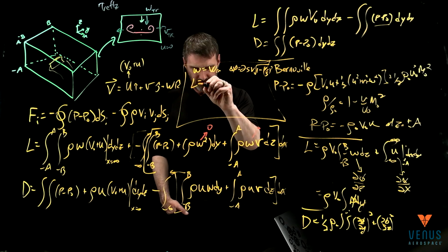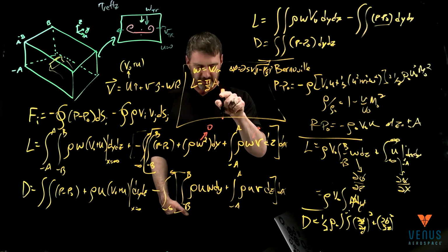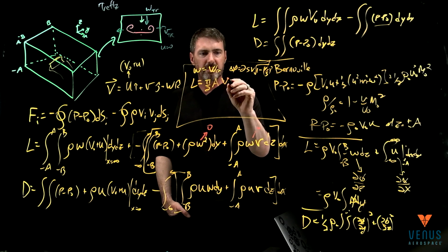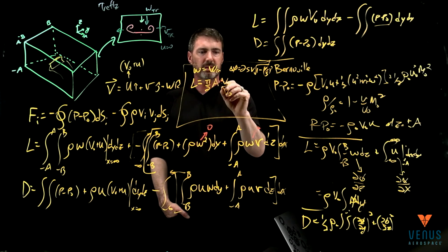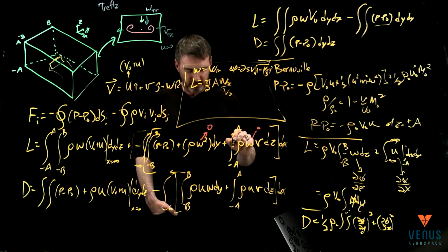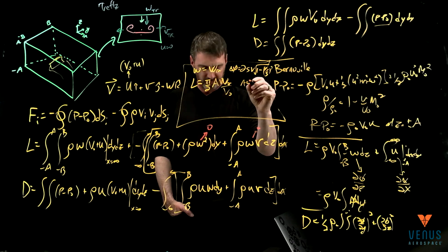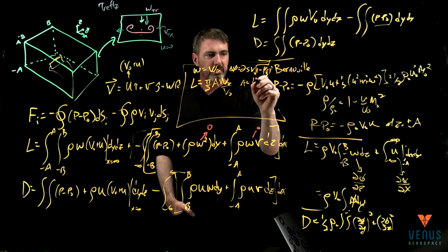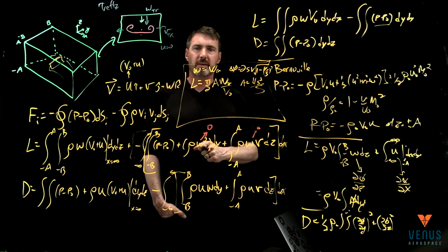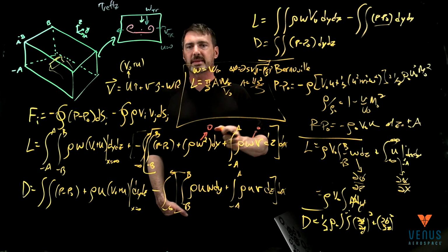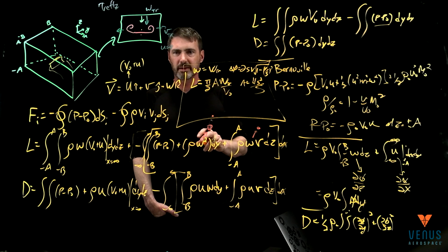So you get lift is equal to pi over 2, and then you pick up your aspect ratio, which is awesome, times that velocity over v0, the downwash velocity, where A is defined as the aspect ratio. So 4 times the span squared over area, and that's a little less versus a big S. That's normally why I try not to change the variables, trying to keep as close to the textbook as I can.